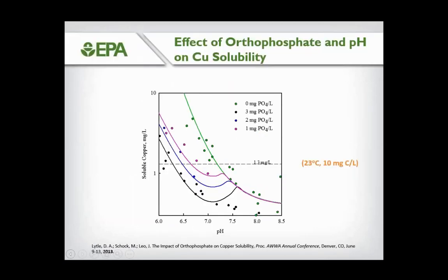risk copper level. Now if you do have high alkalinity and high carbonate content, basically the two approaches would be to either remove carbonate by some kind of lime softening or split stream membrane filtration or anion exchange or something. The other approach is adding orthophosphate. And orthophosphate will work, but you have to have enough of it. And if you don't add enough of it, you actually make the problem worse by perpetuating the newer surface conditions because the phosphate inhibits the aging.